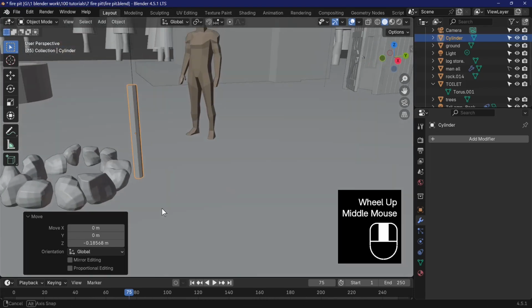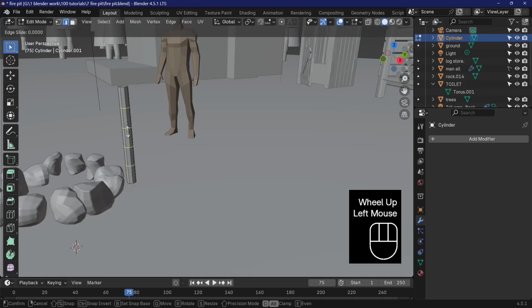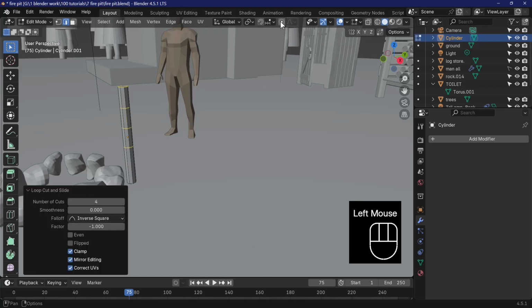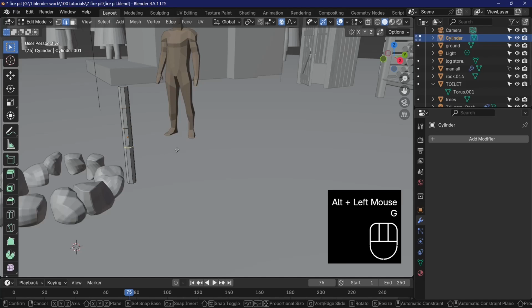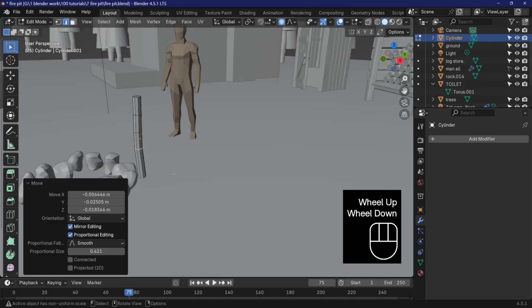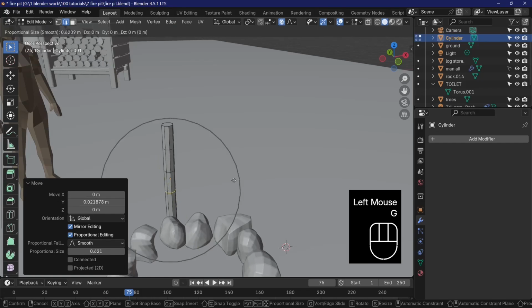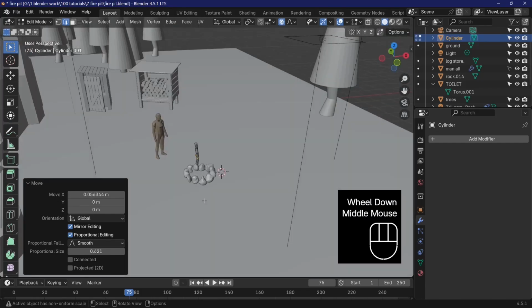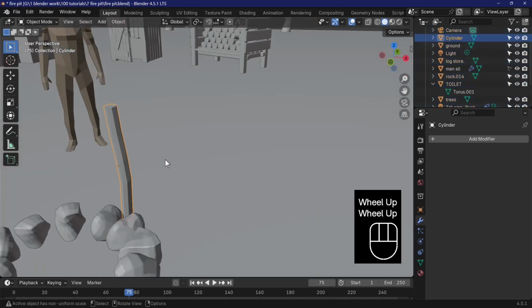Now this could be something that we use to hang our pot from, but as always, let's add a little bit of distortion. So add a few loop cuts, hit the proportional editing, and we'll just move this to one side just to grow our influence ring. And what we can do is make it slightly distorted to give it a bit of life. G and Y, going to move it, and G and X, just to distort it ever so slightly.